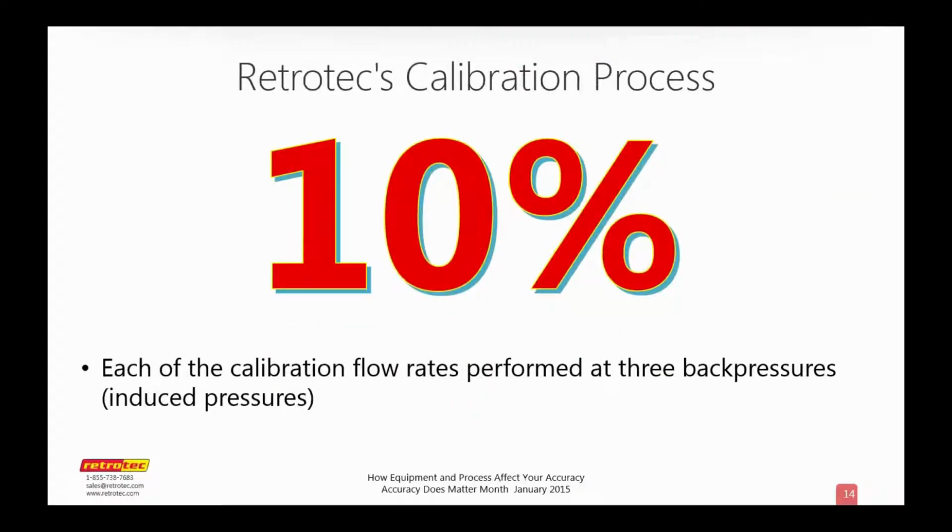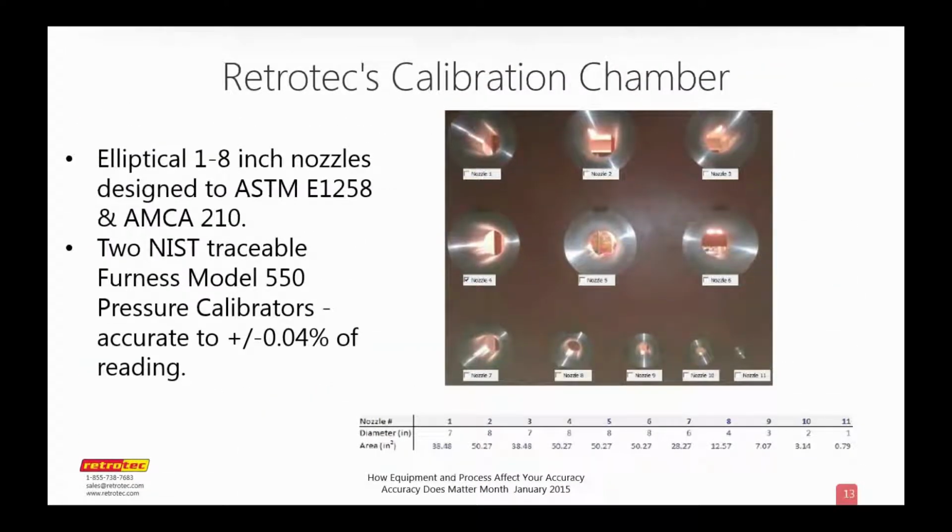I could make a small comment on it. Those nozzles that are in that nozzle wall are what the effective leakage area will measure. So when you measure the holes in those nozzles, the area of those holes is effective leakage area. It's typified by an elliptical nozzle. It's a bit technical, but it's just to give you an indication of what effective leakage area measures versus equivalent leakage area.